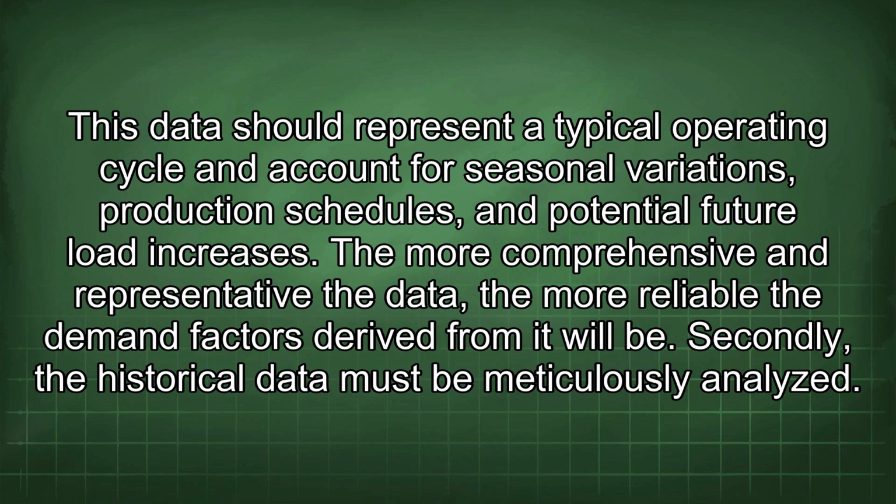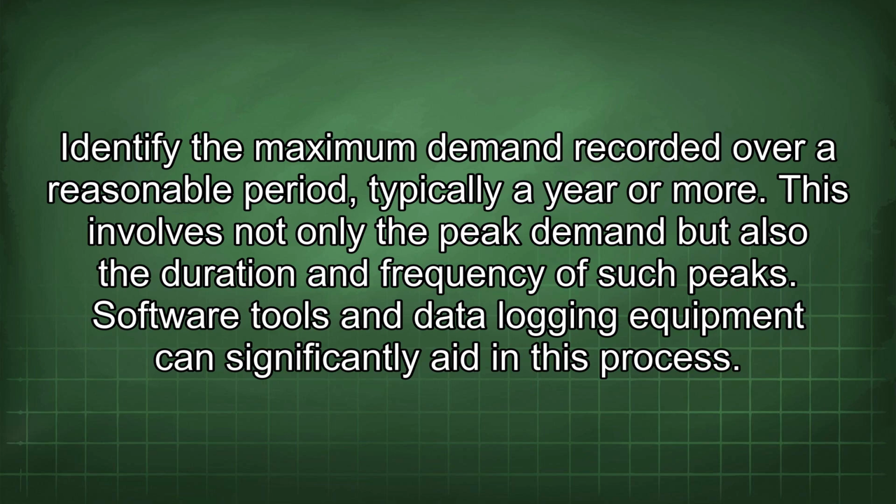Secondly, the historical data must be meticulously analyzed. Identify the maximum demand recorded over a reasonable period, typically a year or more. This involves not only the peak demand, but also the duration and frequency of such peaks. Software tools and data logging equipment can significantly aid in this process.